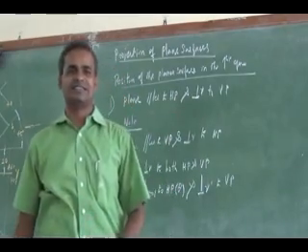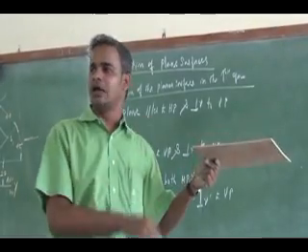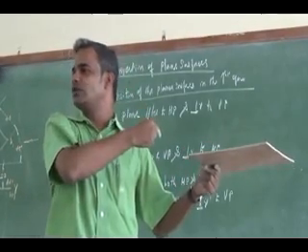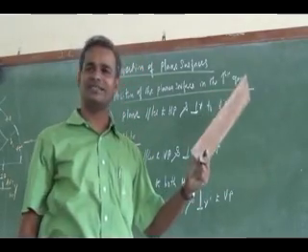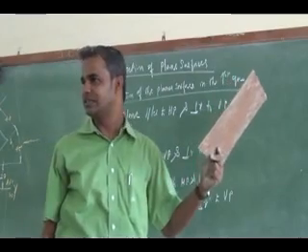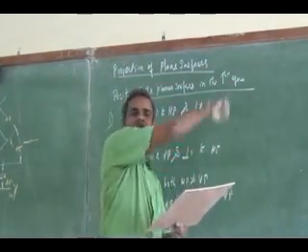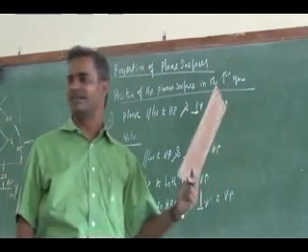So in the first step, in the assumption step, I am making it parallel to the horizontal plane, and I will obtain a length. That same front view length is going to be my final front view length, even though it is tilted. After it is tilted, what is the length of the front view of the straight line? It is going to be the same after tilting.